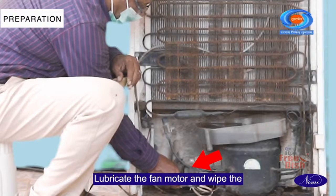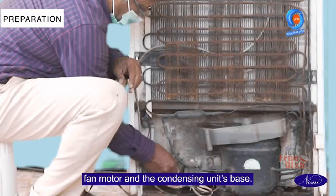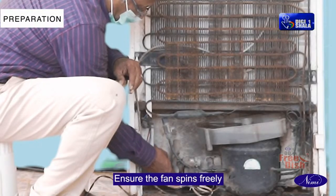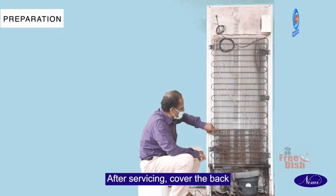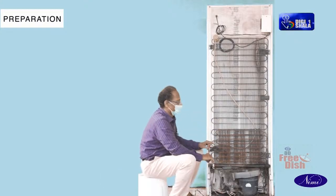Lubricate the fan motor and wipe the fan motor and the condensing unit's base. Ensure the fan spins freely without resistance after cleaning. After servicing, cover the back and securely tighten the screws.